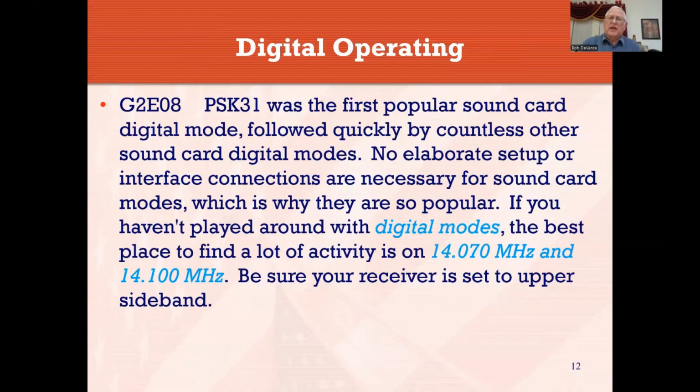That prohibits a ground loop, which causes a loud hum. It just isolates one from the other and eliminates a lot of problems. Generally there would also be a potentiometer, a pot, a volume control adjustment, for each of those. So you could adjust the level of the sound from the radio, and the level of the sound coming from the computer back to the radio.